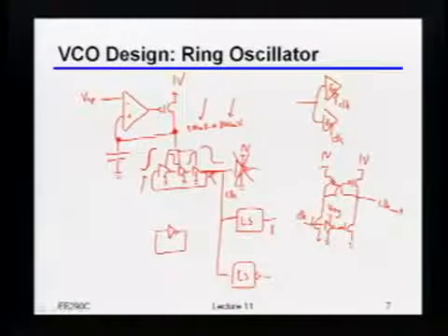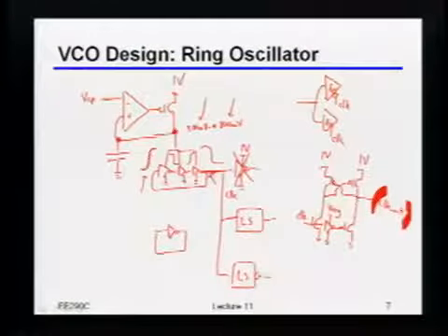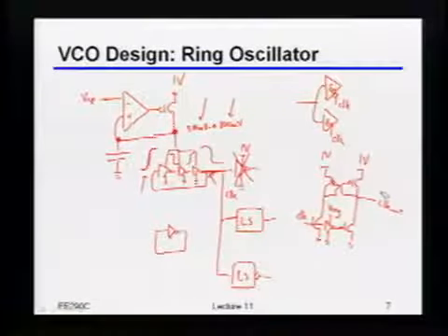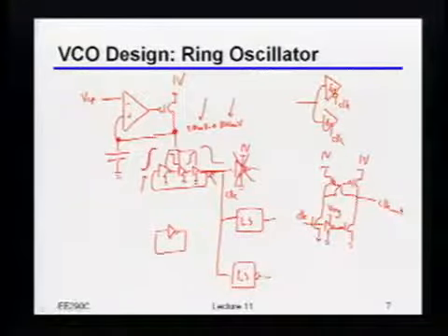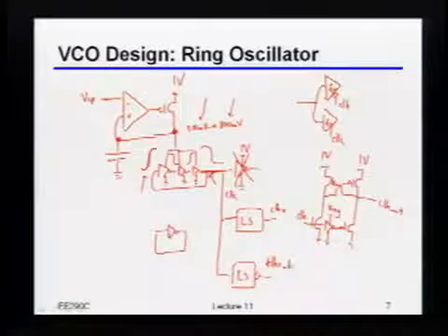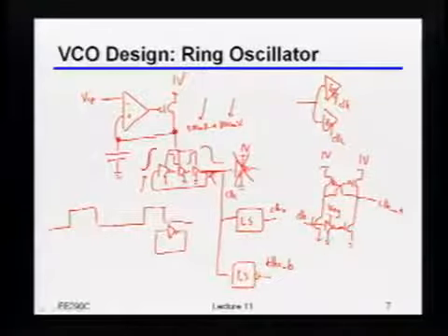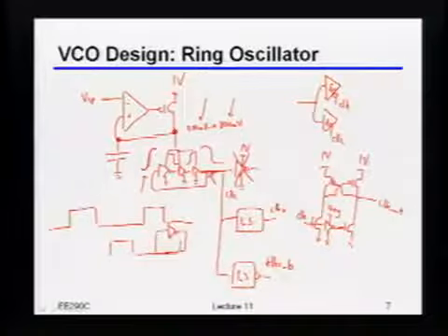So why is the duty cycle not 50% to start? I don't quite get it. Oh, because remember, I didn't do anything to change it. If I looked at the duty cycle of each individual clock, I didn't do anything to fix that, right? So if I draw these waveforms, for example, let's say this is clock O, and this is clock O bar. What I'm basically saying is clock O might look something like this. Clock O bar will look something like that.